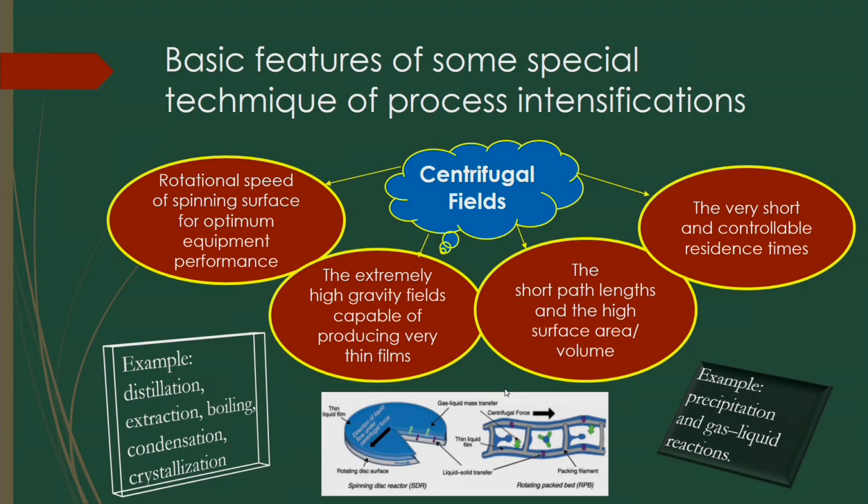So, you have to control the residence time of the gaseous bubbles or any substances or fluids to get more mass transfer. Sometimes for fast reactions it may not be required to have more residence time, so in that case you can operate the upflow reactor, or upflow bubble column reactor, for fast reactions, whereas for slow reactions you have to increase the reaction residence time of the fluid particles by downflow operation.